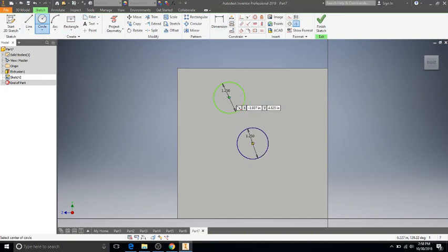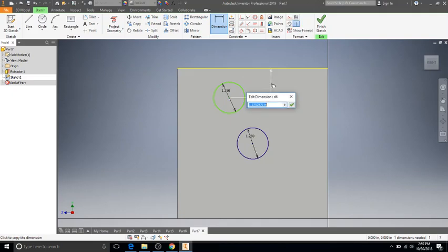You want this center circle to cut the shape in half right there, right? You want this to cut this half in half, so you're splitting the shape up into quarters based on the gaps between the centers of the circles. So from here to here, a quarter of 6 is 1.5. So I'm going to add the dimension between this center and the edge to be 1.5.